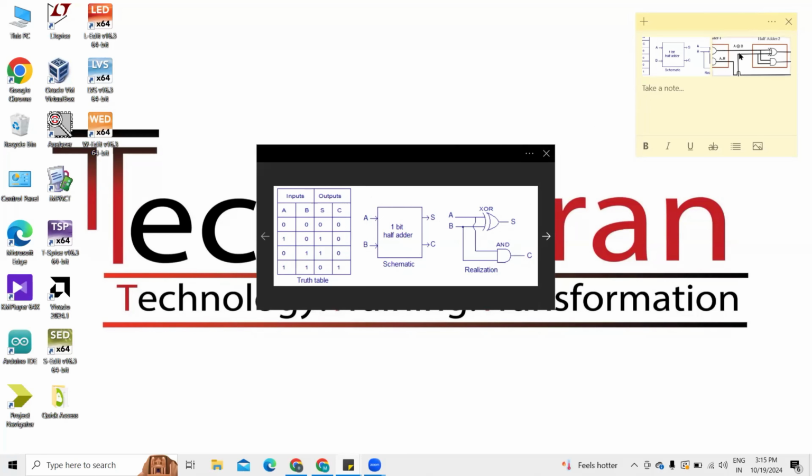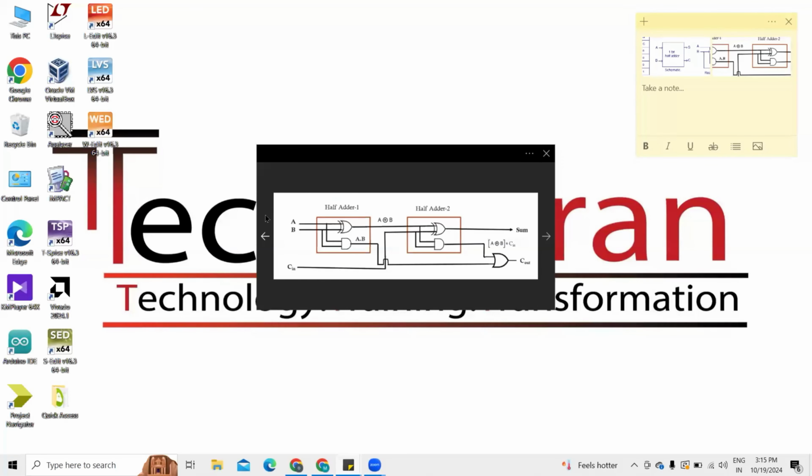Now we will move to the full adder circuit. This is the total circuit diagram of a full adder circuit. If you observe this circuit closely, it consists of three input variables A, B and C in. The full adder can handle the carry input from the previous addition, which makes it suitable for adding multi-bit binary numbers. It uses two XOR gates to get the final sum, and two AND gates along with one OR gate to get the final carry out.